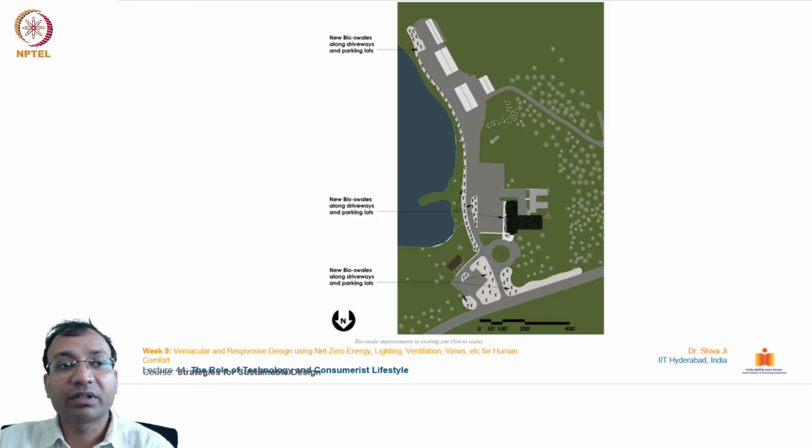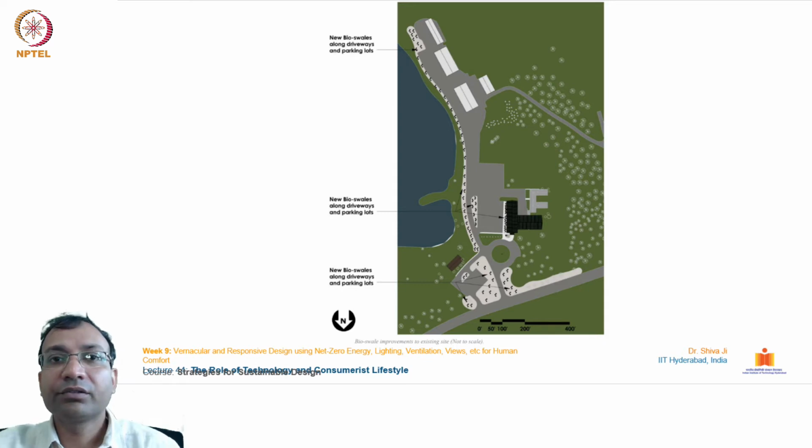Further, I have taken some examples over here for your understanding. This one talks about bioswales. Bioswales are man-made, linear trenches which run for longer distances. They can help us increase the recharge of rainwater to the ground. So you see in this illustration how these bioswales are created along this paved movement place, this road, so that all the rainwater which falls on this surface can get accumulated in this bioswale, and this will help in recharging the ground.